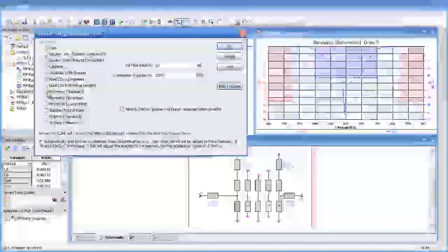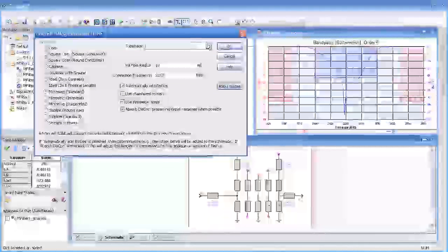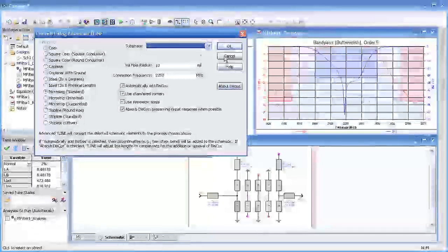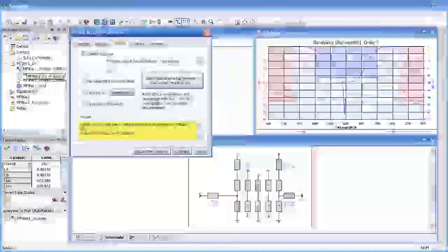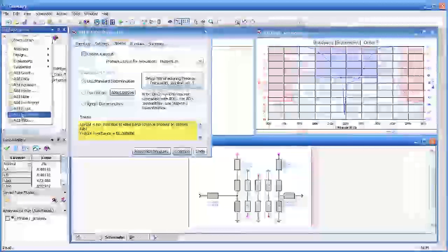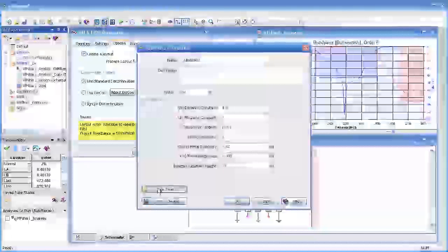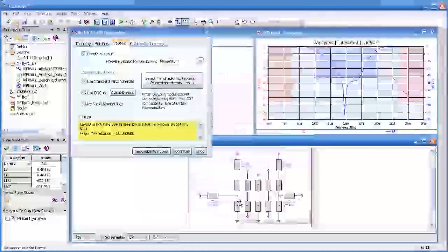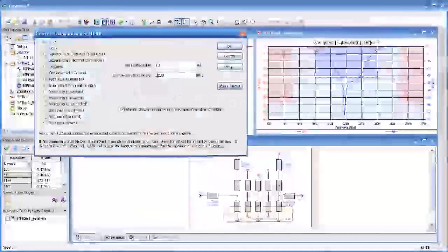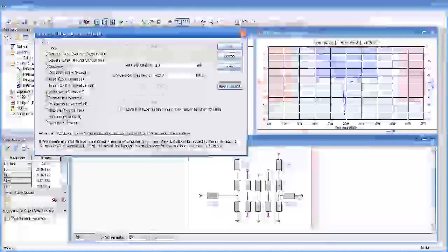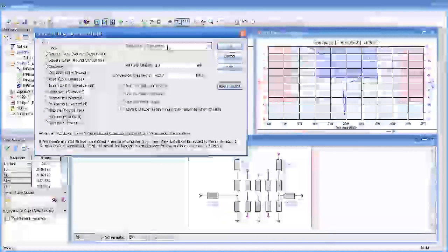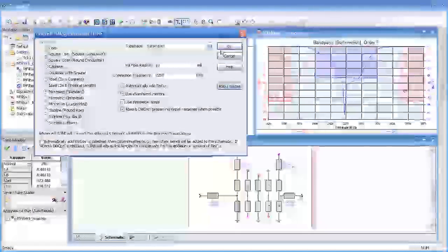You see we have a number of processes available. We're going to select the microstrip standard, but unfortunately we don't have a substrate. So I'm going to cancel out of this, and let's get a substrate into our workspace. I'll do that going over to the workspace tree and then add substrate, and I'll copy an FR4 file over, and we're going to use FR4 for this example. I'll go back to the process and click on microstrip, and now we see our substrate is listed here.